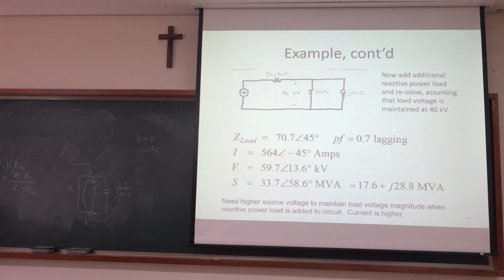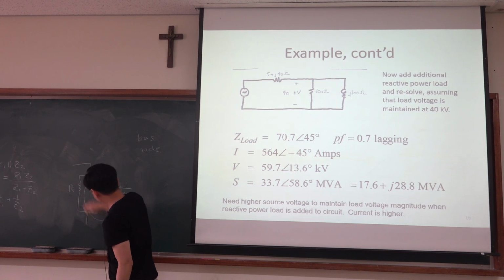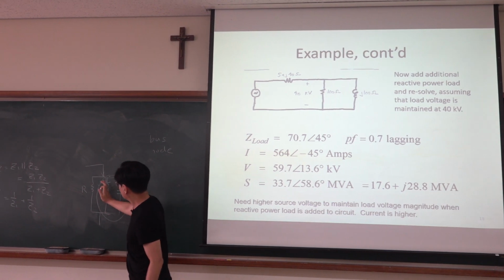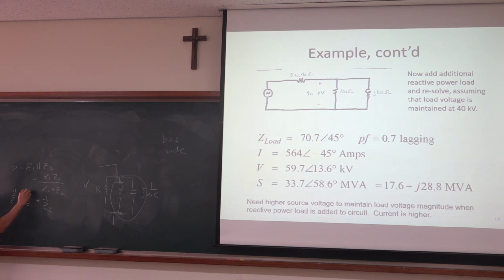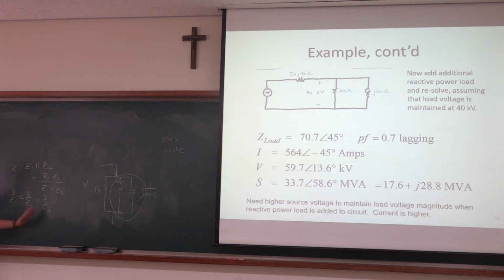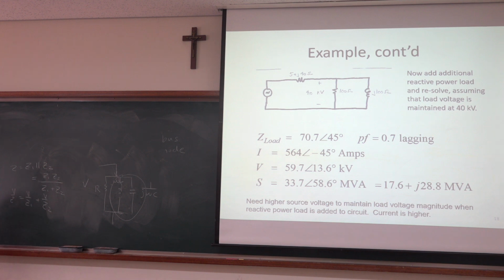You know that. This comes from 1/Z = 1/Z1 + 1/Z2. You remember this, right? The voltage is the same, so the current going through here is the sum of this current and that current. So when voltage V is applied here, the current is the sum of the current for this branch and another branch, right? So from here, you get that. Anyway, just memorize it.